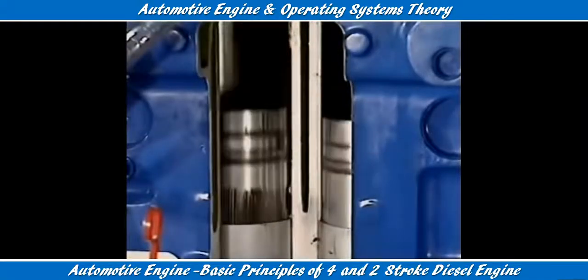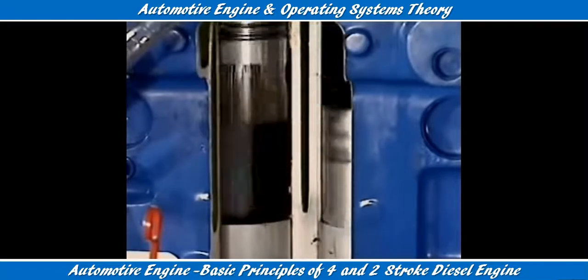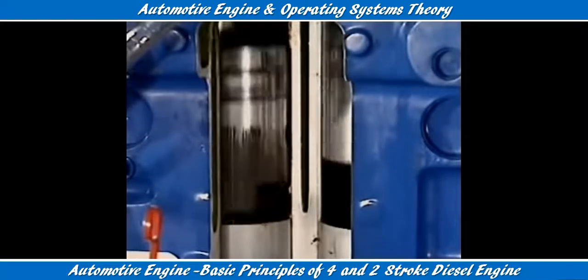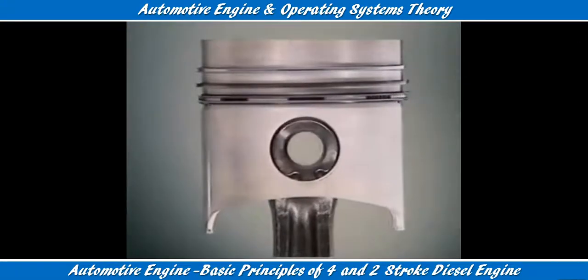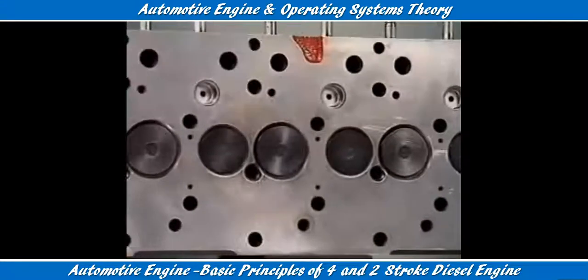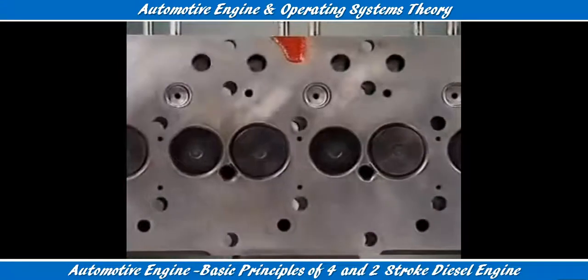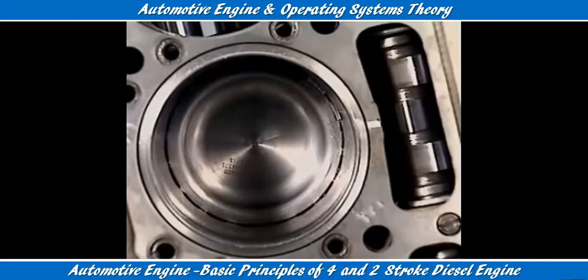Pistons in two- and four-stroke diesel engines can change directions hundreds of times a second and are exposed to extremes of heat and pressure. Modern pistons are made of aluminium alloys. Diesels using direct injection have an almost flat surface on the cylinder head, and almost all of the combustion chamber is in the head of the piston. Engines with indirect injection usually have pistons with a flatter head, and sometimes with small indentations.